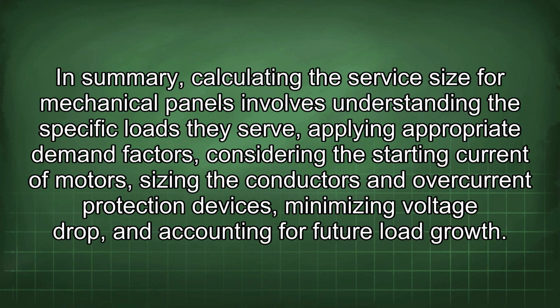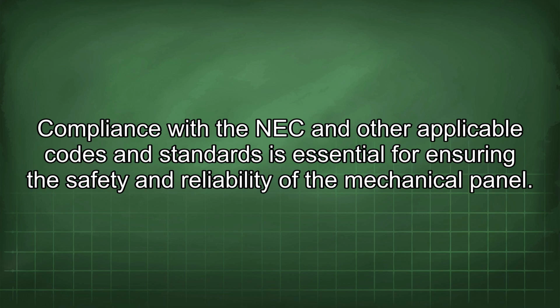In summary, calculating the service size for mechanical panels involves understanding the specific loads they serve, applying appropriate demand factors, considering the starting current of motors, sizing the conductors and overcurrent protection devices, minimizing voltage drop, and accounting for future load growth. Compliance with the NEC and other applicable codes and standards is essential for ensuring the safety and reliability of the mechanical panel.